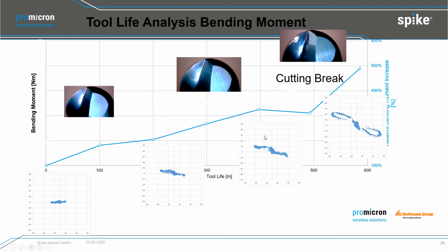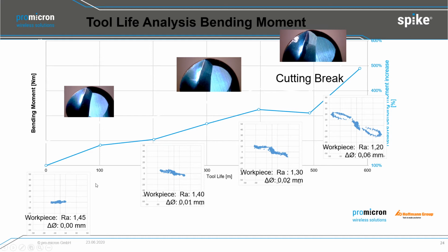And we thought, what is it? And what's the analysis behind that? And by looking at the surface quality, we have seen that the Ra value was getting better and better. That was even strange, but the tool was wearing out faster. The problem in this case was, and this is something for die and mold, the customer told us, which is the most important issue.